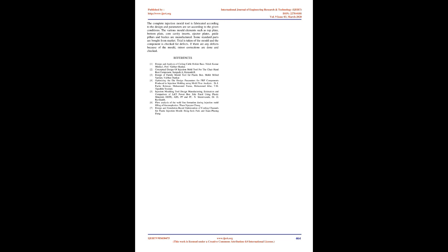Core and cavity. In injection molds usually there are two halves, and the fixed half houses the cavity inserts and moving half houses the core inserts. Since the ejection system is in core side, the component should catch to the same side. Core cavity is extracted using NX 11.0 software and the 10 contact cavities are extracted separately.